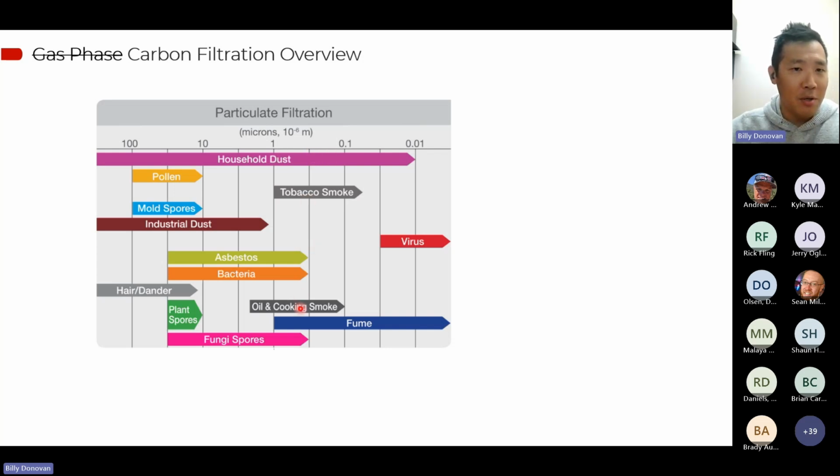So pretty much all of this left-hand side of the chart is well taken care of. For greater efficiencies at the smaller particulate levels, we use HEPAs and ALPAs. An ALPA can be, for example, 99.995% efficient at a 0.12 micron size, or most penetrating particle size. But